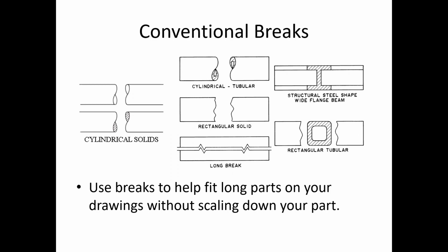For our work, B size on parts is usually pretty good. If we got something really tiny and you want to do it 4:1, if it's on A size, that's fine. I'm not saying never use A size, but I do have some students that just get stuck using A size all the time, no matter what scale they have to do, and it's really hard to get the dimensions to look neat. They're simply too crowded. So 1:1 is ideal regardless of sheet size.